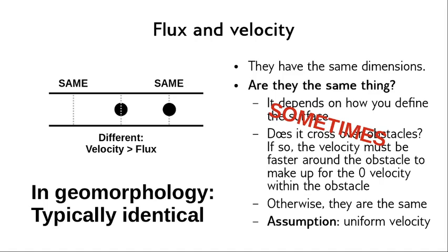In something like groundwater, you might deal with some of these obstructions in the middle all the time, in ways that you can't actually observe or measure directly. Things like when working with flow through porous media, you might be able to know what the area of some wall of an aquifer is, but you don't actually know from direct observation, unless you have a lot of cores, where every single sand grain is. And even if you have a lot of cores, you haven't observed every sand grain. And so what you have to do is figure out, based on some porosity, the relationship between the flux of material and the velocity. So those are different.